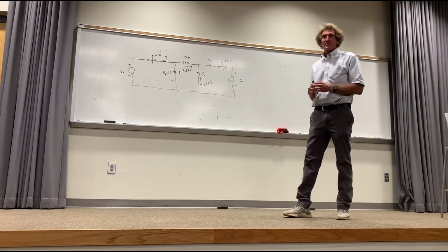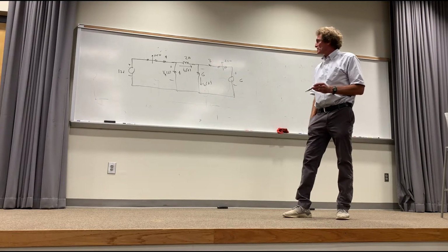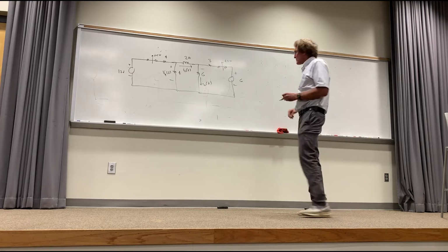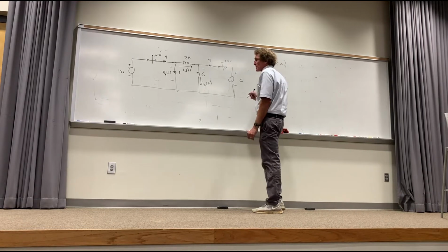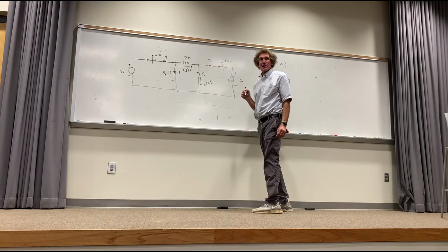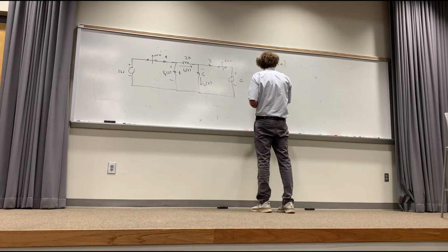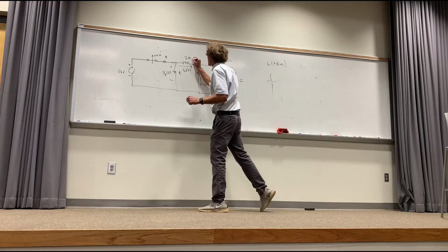This isn't going to be as tough as I wanted it. I could make it as tough, but for now we'll do this one. You have the solution for this. You all see this? Everything applies the same as before. First we find the current IL, T less than or equal to 0. I'm going to redraw the circuit. For T less than or equal to 0, what does that inductor look like, people? Short circuit, right? So it's going to become a short circuit. I'm going to redraw this. Is that inductor 2 Henries? 2 Henries. It should be 2 Henries.